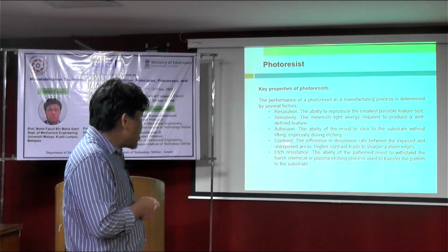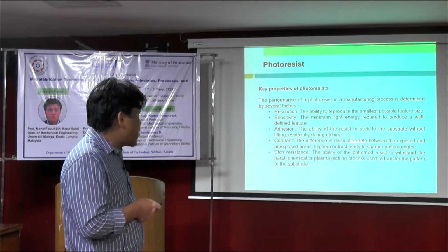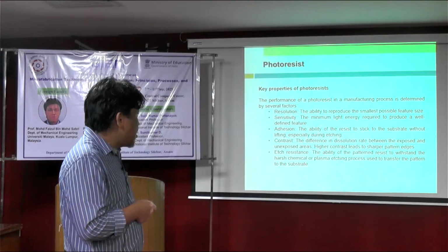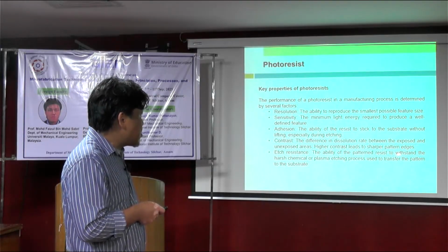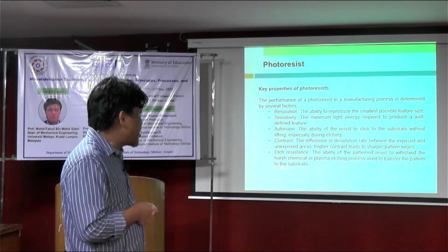And contrast, the difference in dissolution rate between the exposed and unexposed areas. Higher contrast leads to sharper pattern edges. And etch resistance, the ability for the pattern to withstand the harsh chemical or plasma etching process used to transfer the pattern to the substrate.